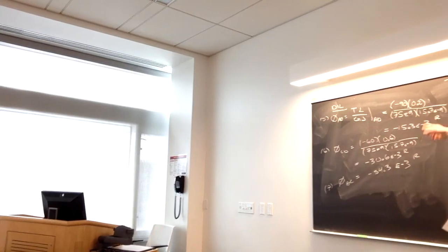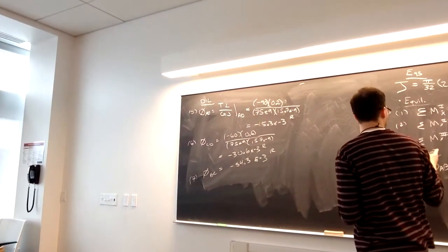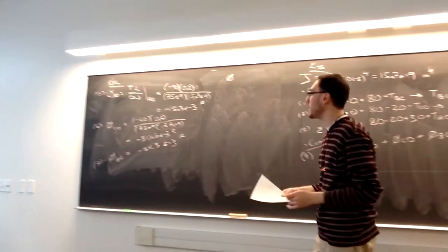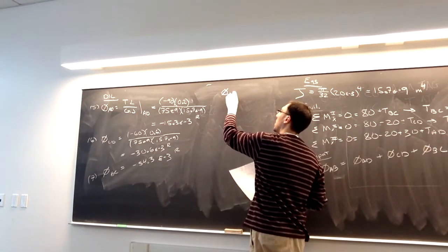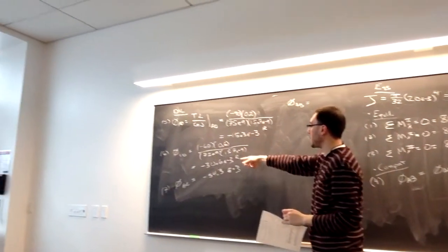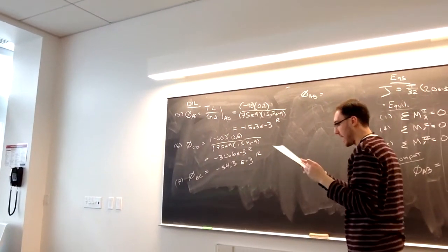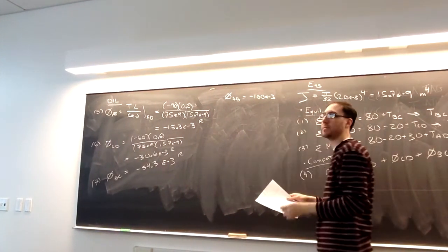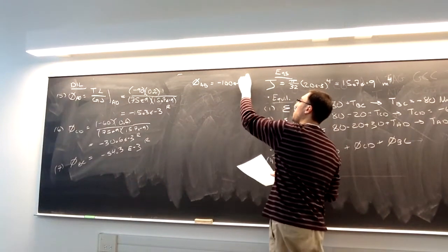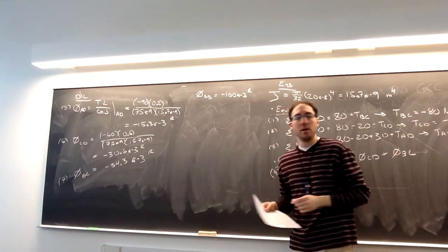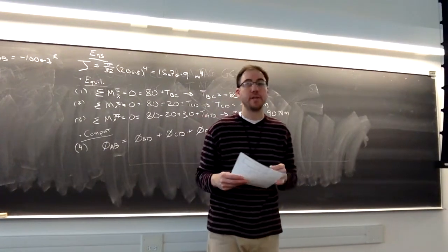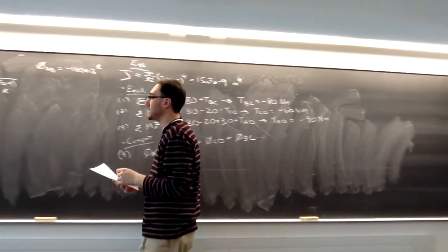I can use my results from 5, 6, and 7 in my equation 4, and I can get what the total angle of twist is going to be between A and B. I just have to add these three numbers together. I get, with some rounding here, negative 100 times 10 to the negative 3 radians. So finally, when I'm talking about my angle of twist of that free end, I want to interpret what direction that's actually going to be.